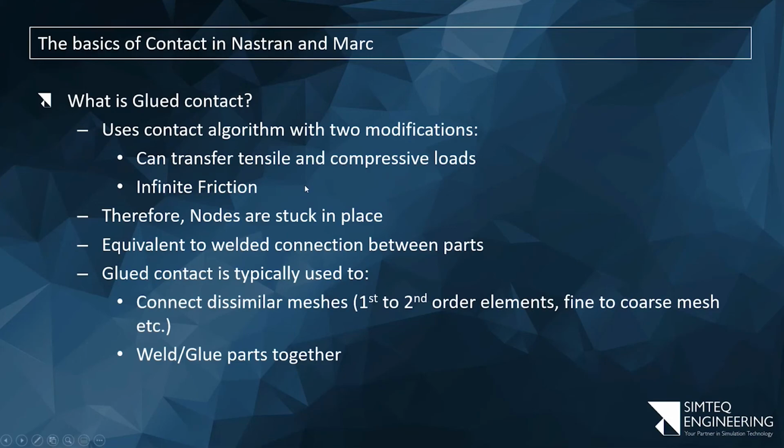The only thing that we typically see that's even more nonlinear is friction, because initially it's stuck in place, the sticking condition. Then we need to load it until it exceeds the normal force times the friction coefficient, the static friction coefficient in this case. The moment it exceeds that, it takes away the constraint, which effectively was an infinite stiffness sideways, and replaces it with a force. That force is now simply the normal force multiplied by the friction coefficient, the dynamic or kinematic friction coefficient in this case, and the direction of that is opposite to the sliding direction.